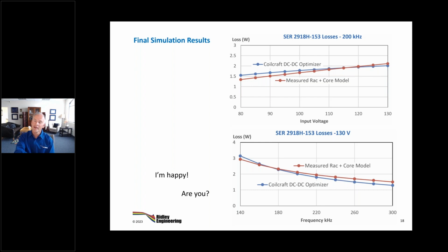But with our model, we can now take this LTspice model of that inductor. You can put it in any topology you like, and you will get a good prediction of what the dissipations are going to be. So it doesn't have to stay within the domain that's being characterized. We want a circuit model that we can lift and put into any circuit.